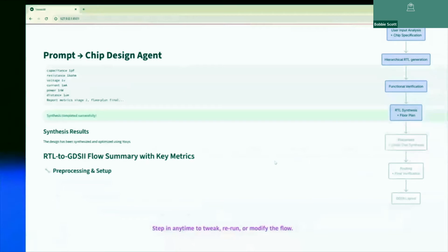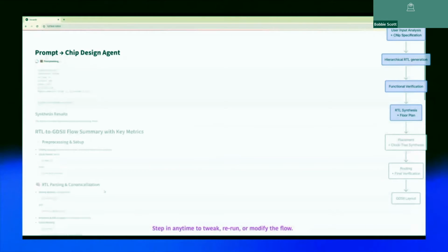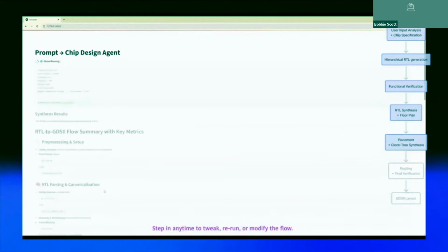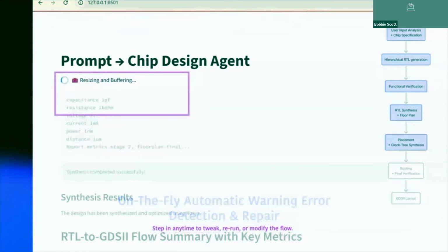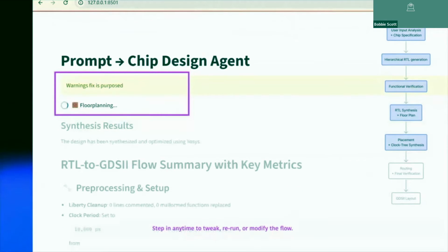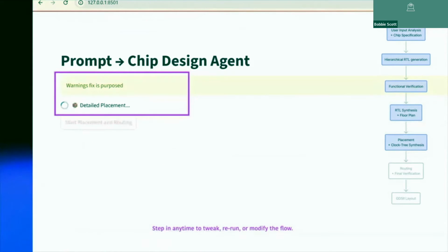The physical design basically involves more than 160 tools. And here we use the open source tools, called OpenROAD. And we use the agent to interact with all these tools. And we give our human constraints to that, expert constraints, for example, power, area, or sizing. Then the agent will interact with the third-party software and optimize that. You can see that there are different stages we did: placement, routing, timing, and the clock tree. Then this is automatically doing that.